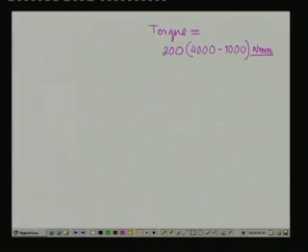So, what we find is that the torque can be written as how much? It is 200 multiplied by 4000 minus 1000, and the unit will be Newton millimeter. So, this comes out to be 600 into 10 to the power 3 Newton millimeter.